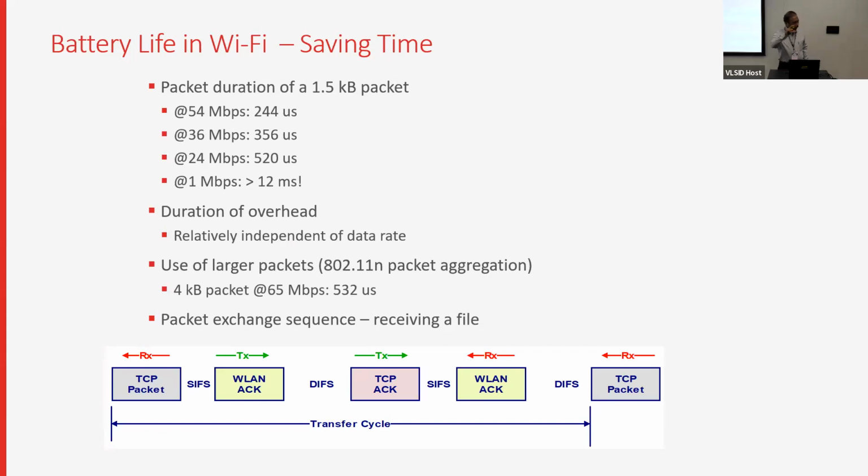And remember that if your front end is on and your MCU is on, current consumption is the same. So here you're using about 12 into 4, 48 times the energy for receiving the same 1.5 kilobytes packet. Right? So the faster you can finish it, the better.